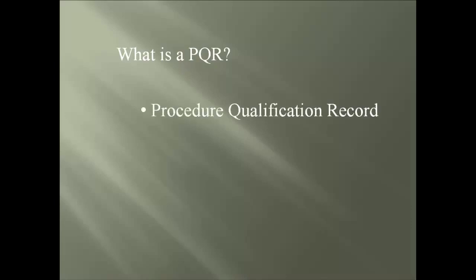First, let's start with the basics of the PQR, and that is to answer the question of, what is a PQR? The letters PQR stand for Procedure Qualification Record, and this is a living document of the actual welding variables and test results that were used to produce an acceptable test joint.